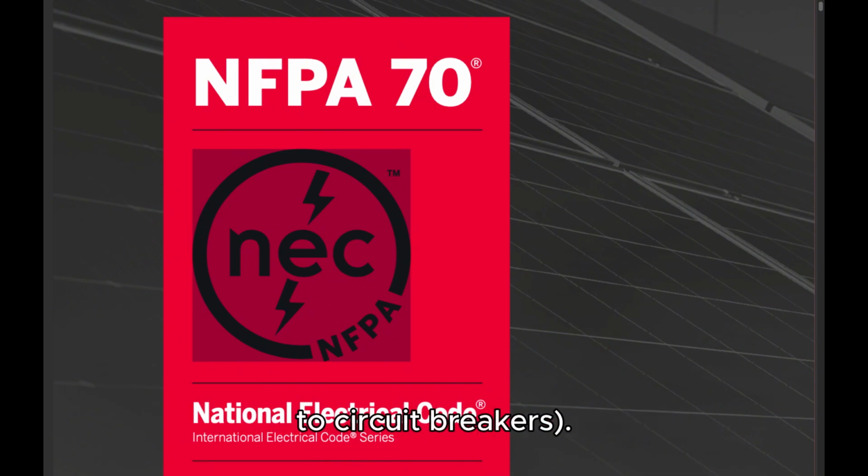Non-adjustable as applied to circuit breakers. A qualifying term indicating that the circuit breaker does not have any adjustment to alter the value of the current at which it will trip or the time required for its operation. Setting of circuit breakers. The value of current, time, or both, at which an adjustable circuit breaker is set to trip. Clothes closet. A non-habitable room or space intended primarily for storage of garments and apparel.